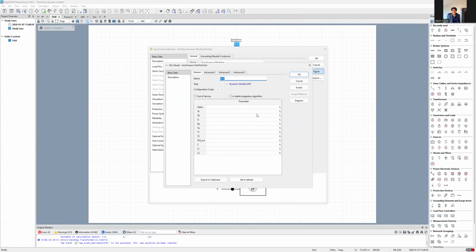Okay. And the AVR, there are different parameters, limits. So can I write it? This is like if DLIM, it's a field current limiter. We are not going into details, but I would like to emphasize it. And TA, and don't get confused about what is TA, TV. These are just the time constants of different blocks. When you go into dynamic models, how the control system works according to input output relationships, you will be familiar with it. Right now we just copy it.